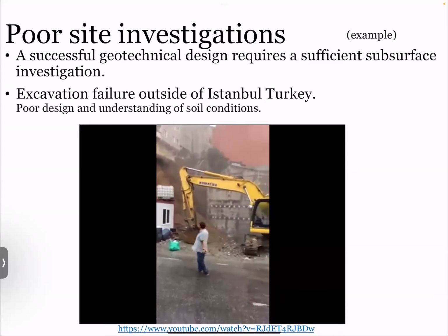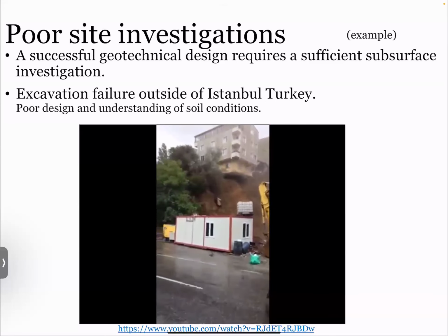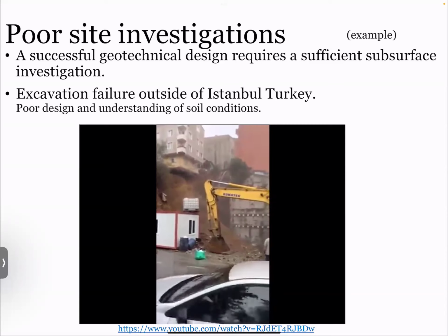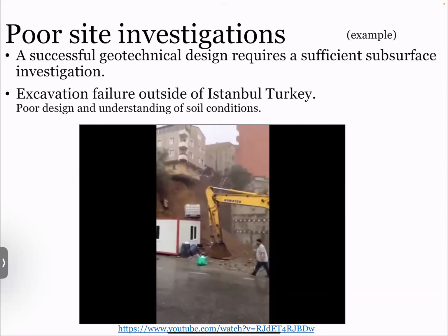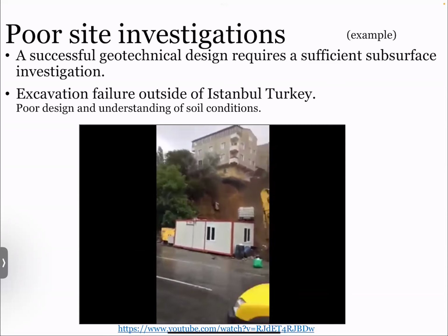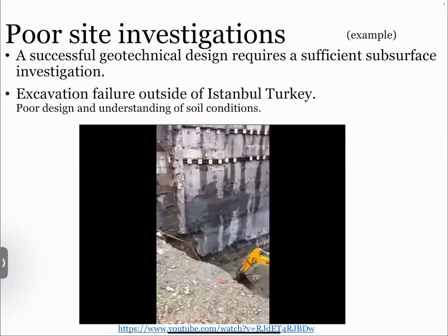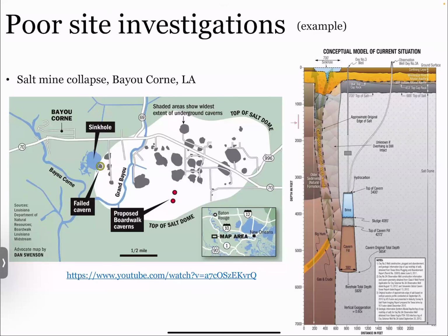Did we have a good understanding of the site conditions? Is this soil pushing on the wall more than we would have thought? Did we design that wall correctly to account for that? Did the structure on top play a role at all? Anytime you have a failure, it's always going to go to that first subsurface investigation report, which is why it's important to understand these things.